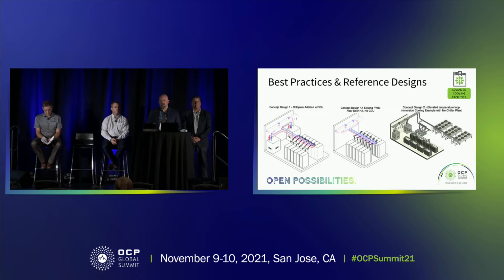So we've got facility water, or the chilled water loop, so to speak, which we're calling an OCP facility water. And that's going down to a couple CDU units, which are in redundant fashion here. And they are doing a couple things. They're bringing the pressures into the right ranges and also the temperature. So it's an isolated loop separate from the building system.